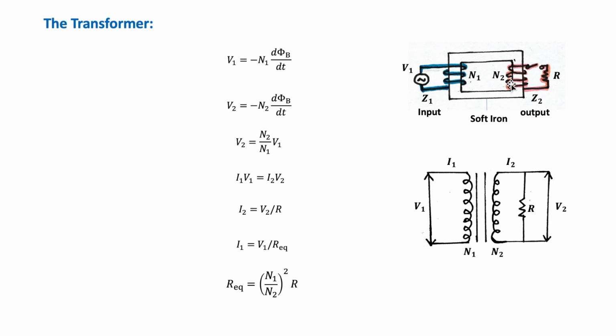So now suppose the switch in the secondary coil here is open, and suppose the resistance of the primary coil is negligible. Then the primary circuit is equivalent to a simple circuit consisting of an inductor connected to an AC generator, right? And in this type of circuit, as we have seen previously, the current is 90 degrees out of phase with the voltage, and so the power factor that we discussed in the previous slides, which is cosine phi, will be equal to 0, because cosine 90 is equal to 0, and therefore the average power delivered from the generator to the primary circuit is zero.